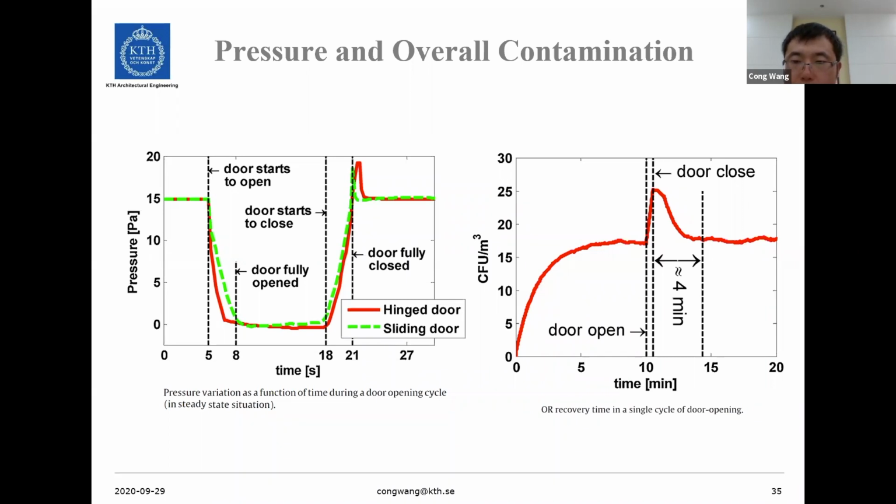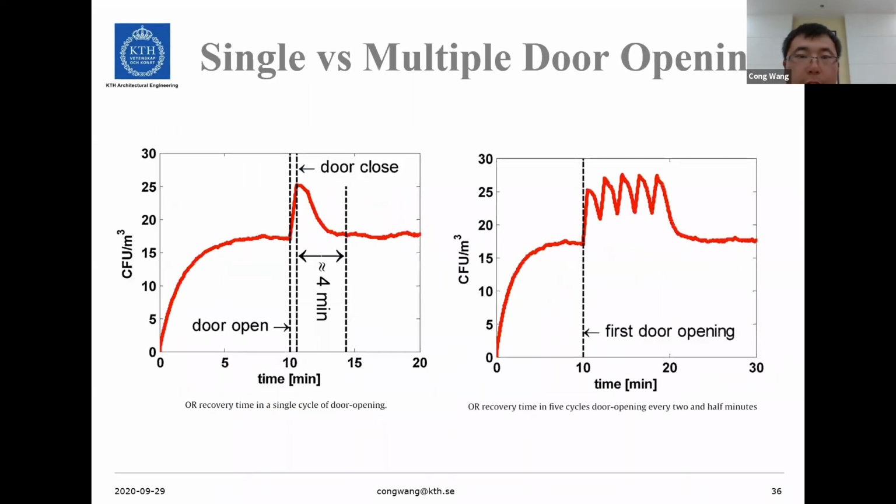And this 4 minutes, we usually call the recovery time. So this is the single door opening. It takes 4 minutes to recover the original contamination level.